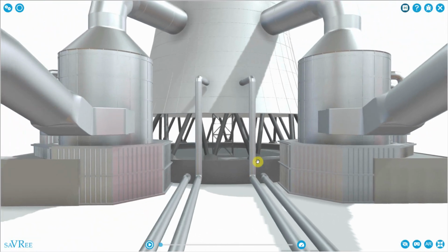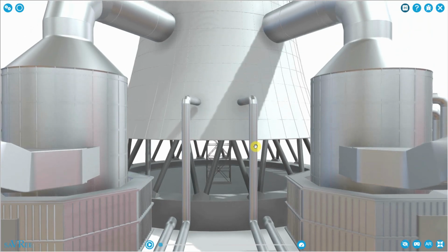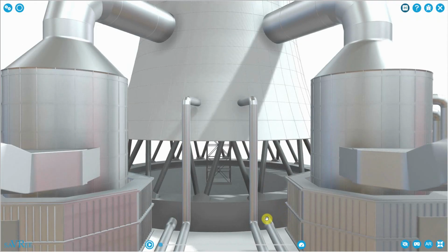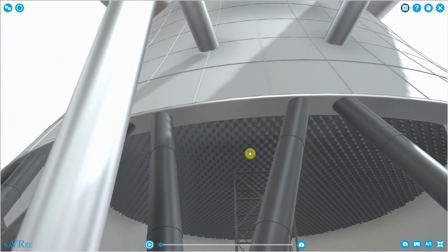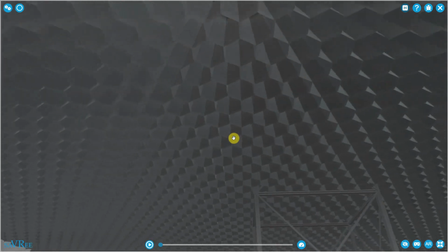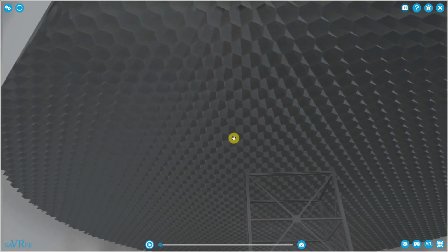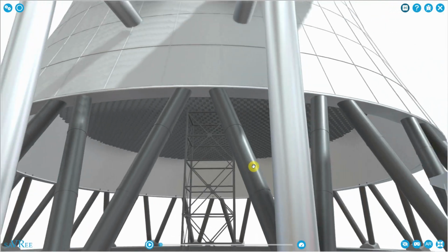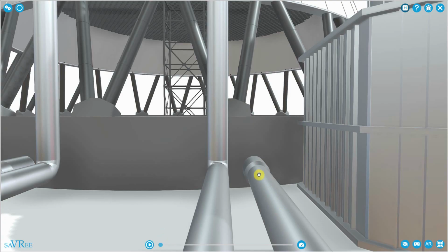I know this because the water from the condenser, when it's sent back to the cooling tower, is delivered higher up into the cooling tower than when we're drawing it out through the base towards the condenser. The water enters into the cooling tower and is sent into a heat exchanger. You can see it here. And the water is going to drip down through that heat exchanger. Some of it will evaporate, and this will cause the remaining cooling water to be cooled down. That is evaporative cooling. The cooled cooling water is drawn then through this pipe and sent towards the condenser.